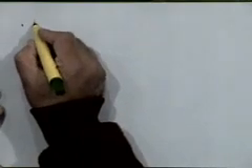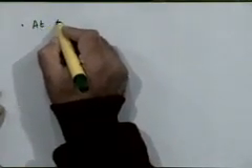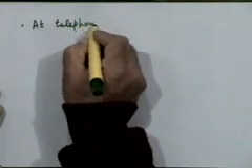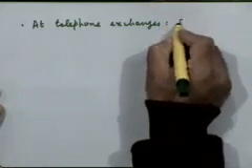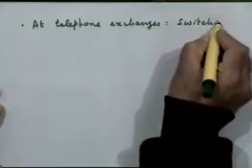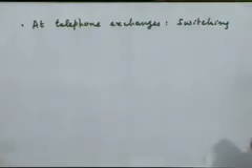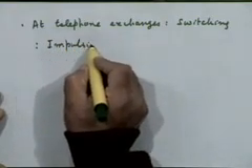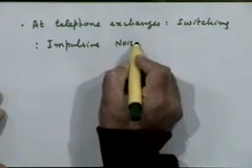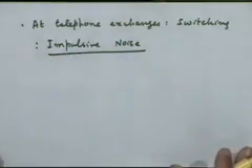So again, at electronic exchanges or telephone exchanges, there is a lot of switching. Any place where there is a lot of electrical switching taking place is a source of radiation for us. Please remember that. And therefore a source of what we typically call impulsive noise, right? You agree with this?